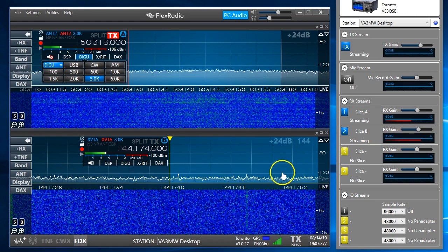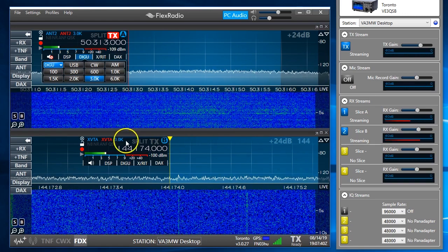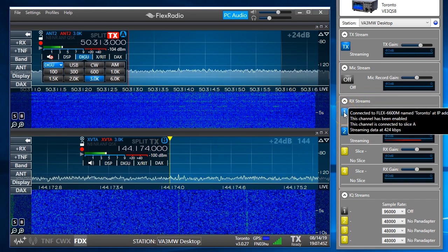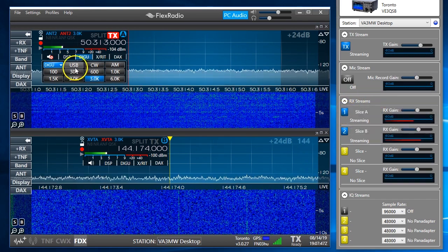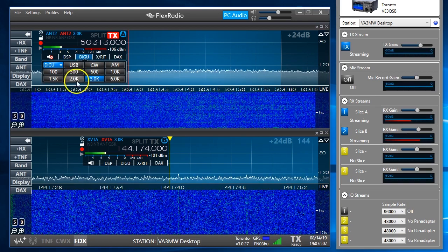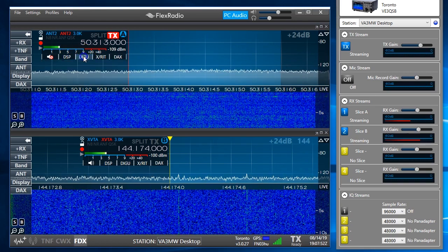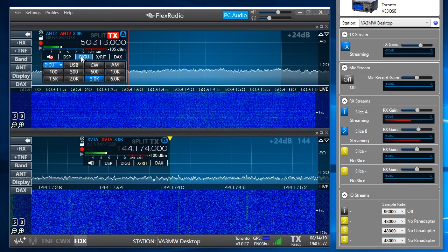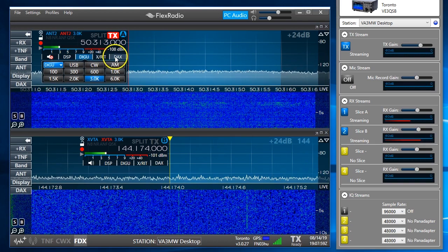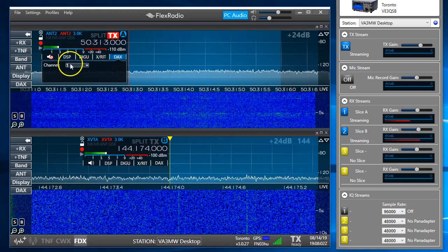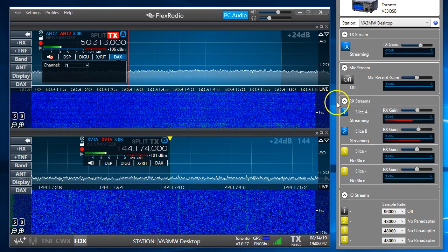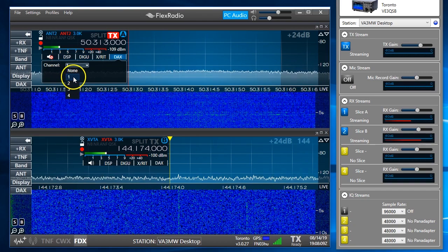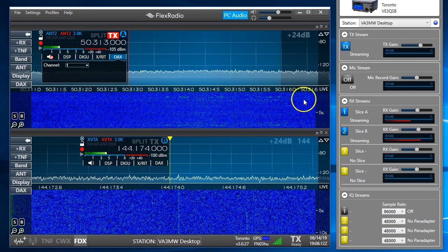So if you're going to digital modes, you do have to have 3 buttons clicked or checked. So this DAX, let's start on the receiving stream, the RX stream. We're going to focus on 1, and then we walk over here, and you'll see it's DigiU. The DSP you'll leave alone. And this DAX is key. This has to be channel 1. That channel 1 is this channel 1. You'll see if I drop it open, there's 4, and that's because we can have 4 receivers. But generally 1 and 1.